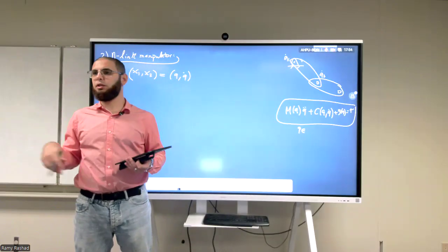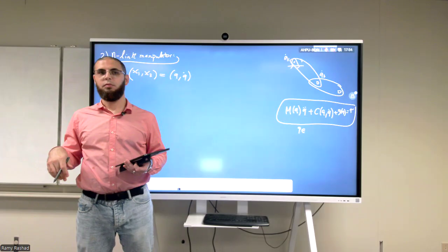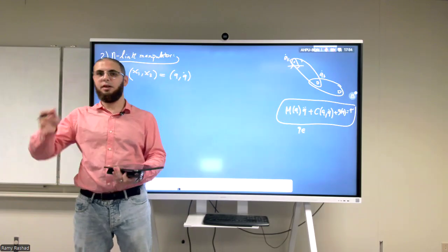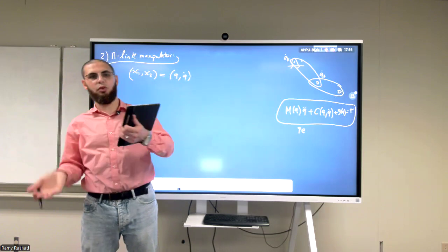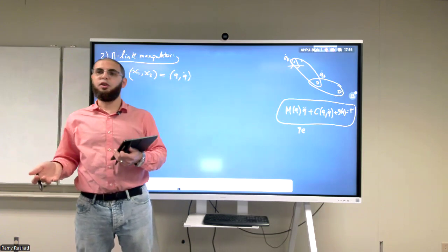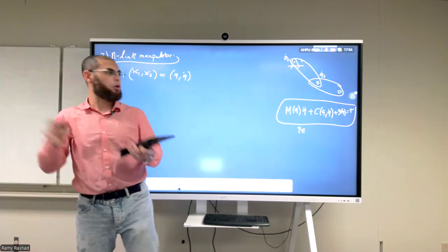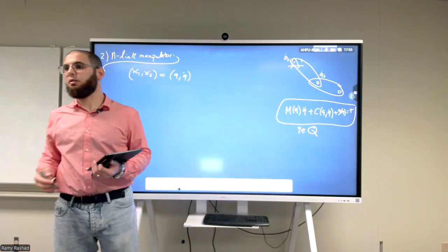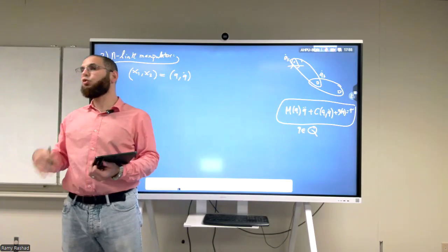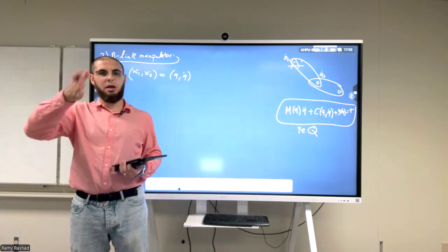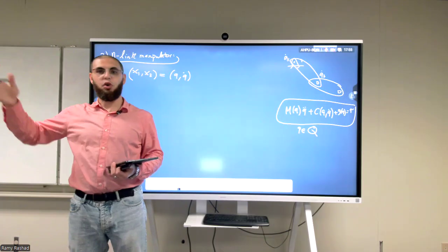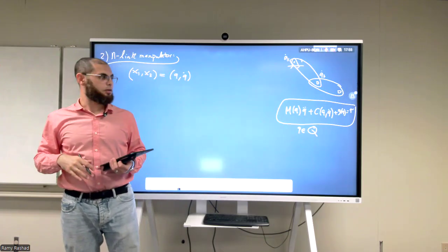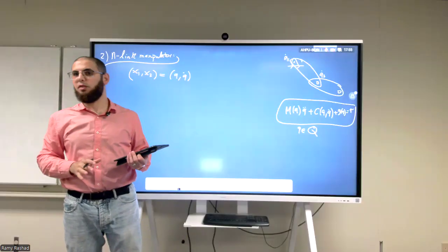What if you have prismatic joints? What if you have a mix, where joint 1 is prismatic and joint 2 is revolute, and so on and so forth? What do we call this? We usually call it a manifold Q, the configuration space, which depends on the joints. It will in the end be isomorphic to a torus cross some R's, depending on how many prismatic and how many revolute joints you have. We just call all of this Q of the manipulator.